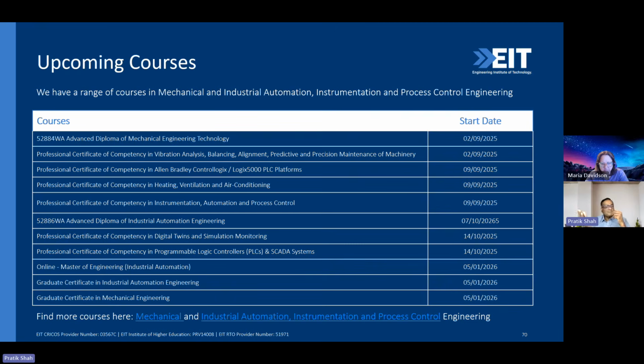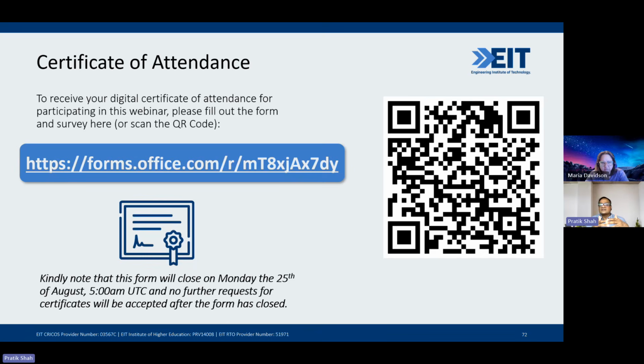Coming to computer-aided manufacturing, it is the most versatile tool nowadays. The conventional machine tools we had, for open tolerances, could machine up to plus or minus 1 mm. But with the advent of CNC machines, you can now talk in terms of tolerances as fine as 10 microns, 20 microns.